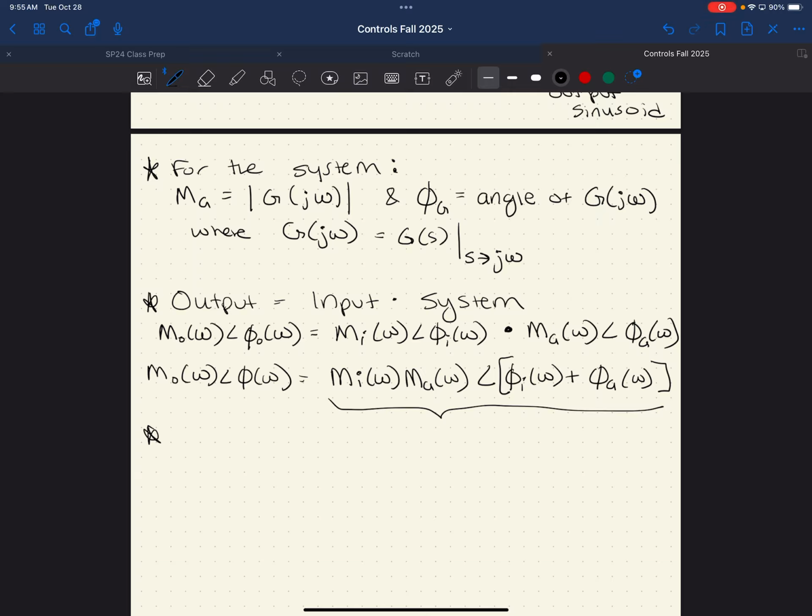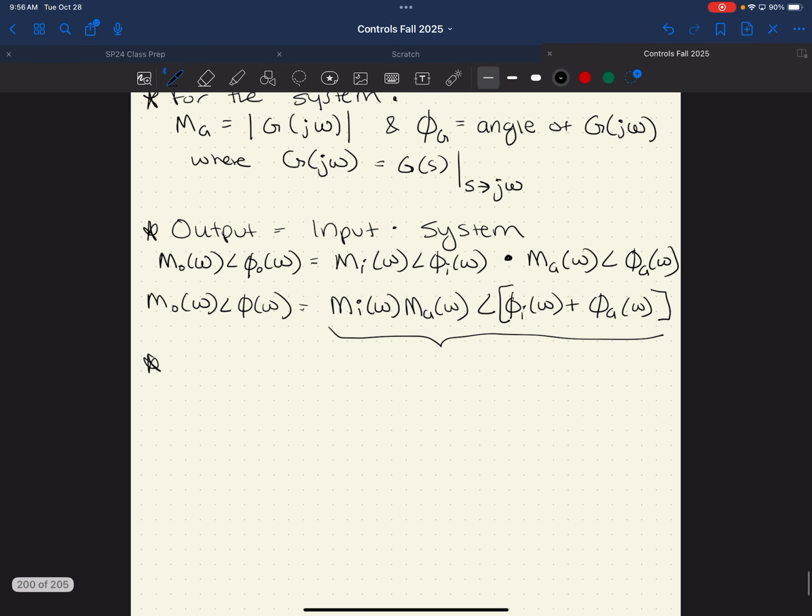What do we already know about maybe a particular frequency that creates some particular response that may be especially bad? Yeah, we talked early on about the resonant frequency, right? So in terms of what we've just covered, what do we know about the resonant frequency? It means that if we force the system at the resonant frequency of the plant itself, then the amplitude is going to get quite large, right? Okay, so let's take a couple notes here.